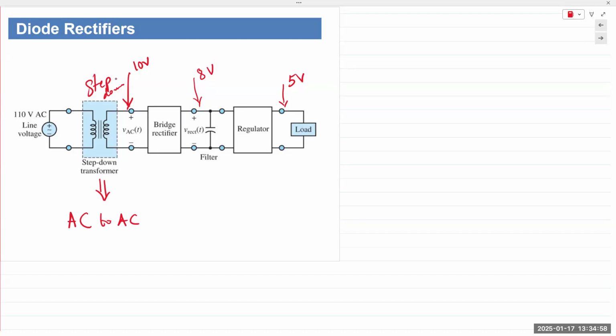And that's how it works. So if you have a metallic case on your smart device, it's going to short circuit that field, and the charging is not going to work. Or if it's very thick, it's physically going to protect your device, but electrically it might interfere because now your device is away and the magnetic fields are not able to interlink.